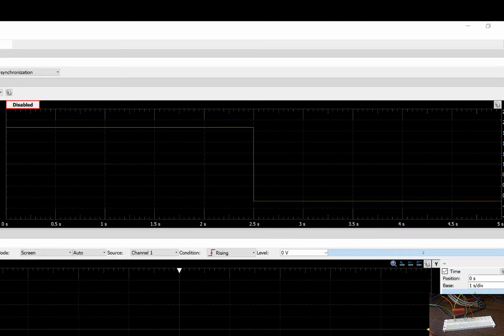We're going to look at two examples of input voltages. The first is a square wave, which supplies a constant input of 2 volts for 2.5 seconds, and then supplies an input of 0 volts for the next 2.5 seconds. Take a moment to think about what you think the output might be before proceeding.